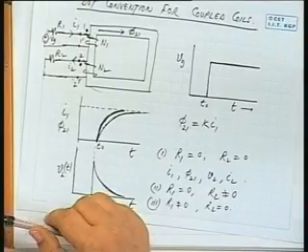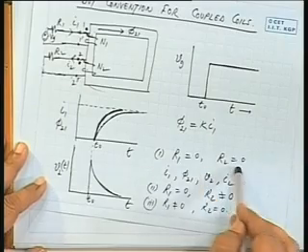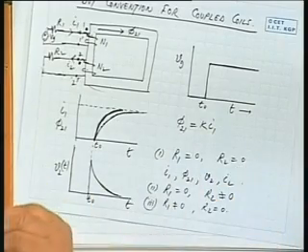So it will be somewhere in between. If R1 is 0 and R2 is 0, what happens? That is, across an inductance, if I switch on a supply as a DC voltage, if I apply it across a pure inductance, there is no resistance, what happens to the current? It is L di by dt, which is constant, V.